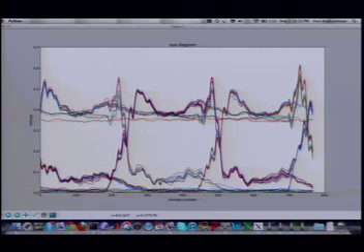Plausible, right? Because the step that we get here looks a lot like the step we're getting here. The deviations might be noise, but the more structured parts of the waveform here match the structured parts of the waveform here. And what you're really seeing is the loudspeaker reverberating through the room. You're all staying fixed, so the echoes are from fixed locations. The walls are fixed. And so what we're seeing is the step response of the room, in effect. And if you hit the room a little bit later, you get the same response, but a little later.